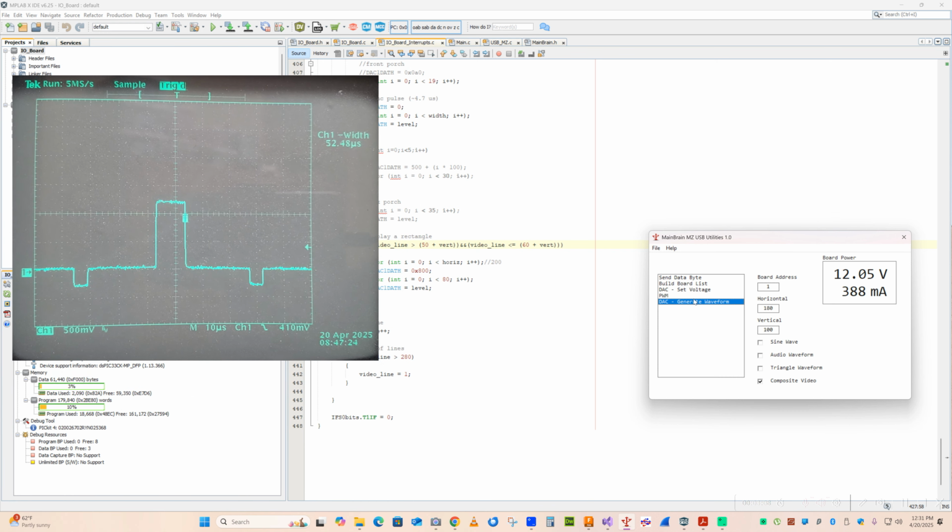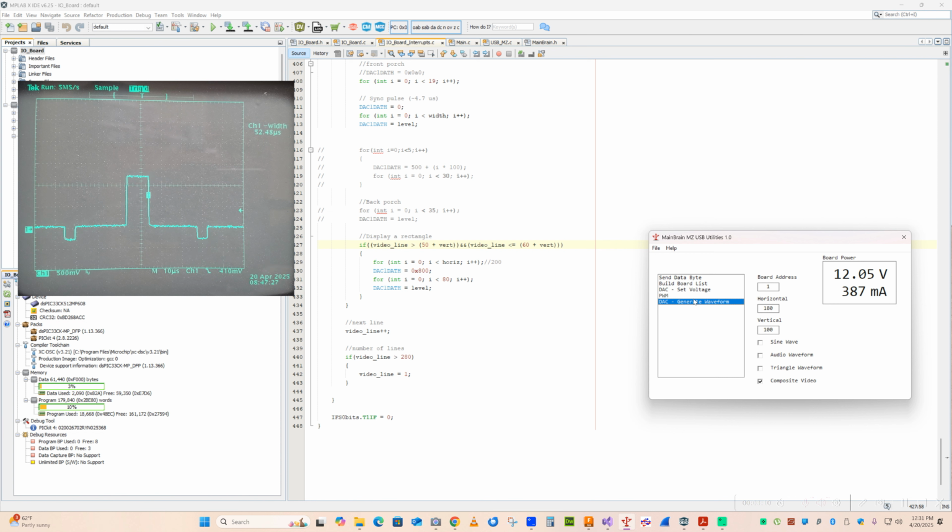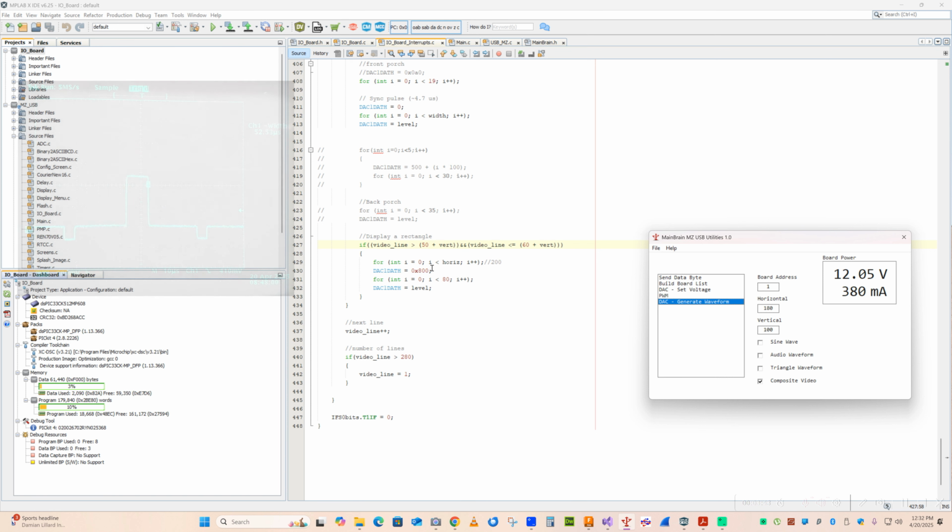The height of the video pulse is, of course, how white it is. So that's why the background information that surrounds that pulse is low, which is black. So you could raise those. You can raise the background level here and make it less dark, or you can flip them and make this a high like an 800 and make this a 300, and it'll flip it to where you have a black rectangle and a white background, or anywhere in between.